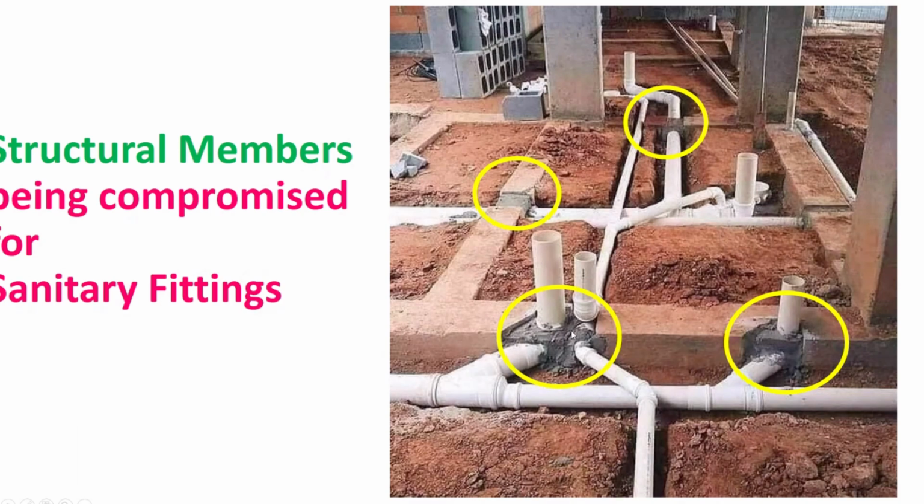Possibly the plan area of my footing may be 2 meters by 2 meters. Then if the bearing capacity is reduced by 50%, then possibly the new dimension may be 4 meters by 4 meters or 3 meters by 3 meters. So please get it redesigned.